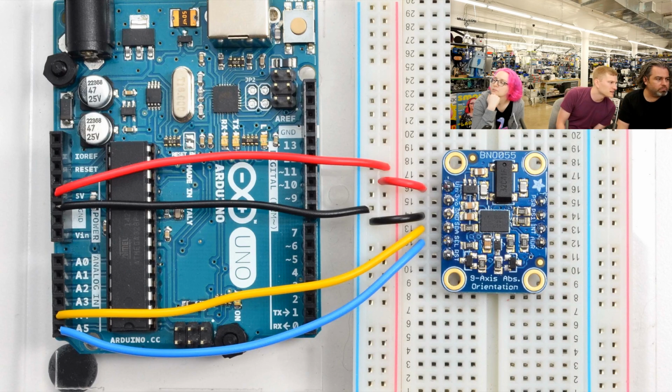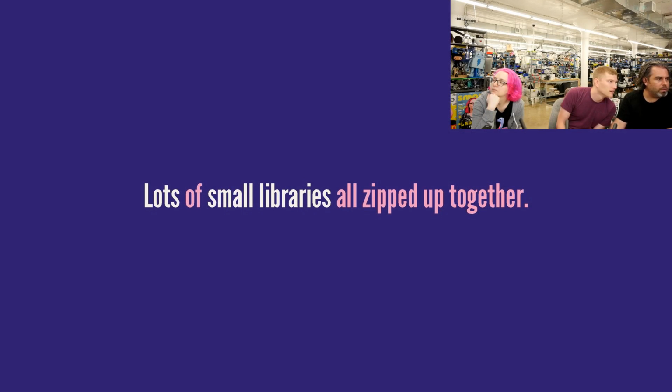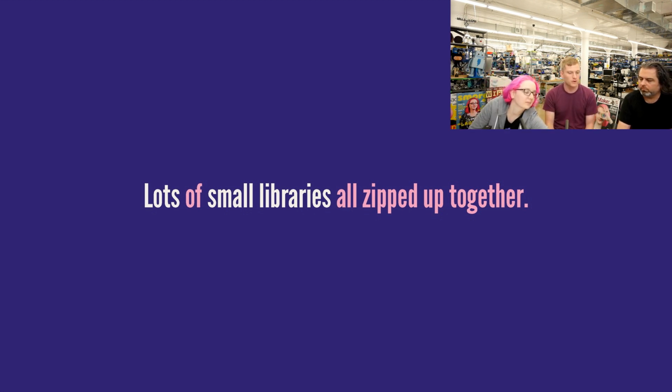So what we would end up with is this model where we're going to have a lot of small libraries that people can use. I think I even talked to you when you asked what we should implement for CircuitPython. I said, first off, get a UART or a REPL going. Then digital I/O, and make sure you can blink LEDs and read buttons.